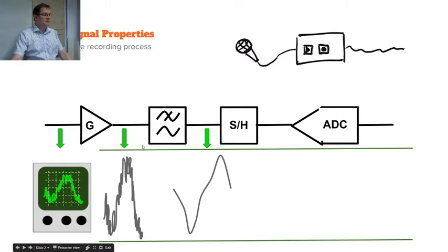Then, after the low pass filtering, there shouldn't be any more of these quickly changing signals. Fundamentally, we have to remove all the frequency components which are higher than the Nyquist frequency. If there are higher frequencies than the sampling rate divided by 2, you have to reduce those.